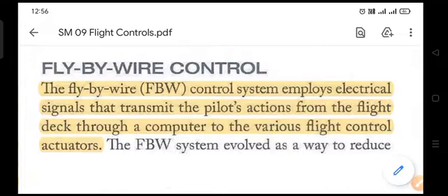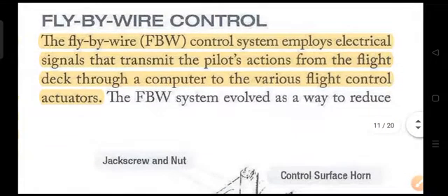Second of all, fiber optics implementation in aviation, you must have studied this in Module 5 also, requires a lot of cost, and maintenance is very difficult, and adequate training is not there with many people. And if not done in a proper way, there will be data loss. So that is the reason till now we have not implemented fly-by-optics in all the aircraft. There are definitely a few in which it has been tested and experimented, and it is used also.